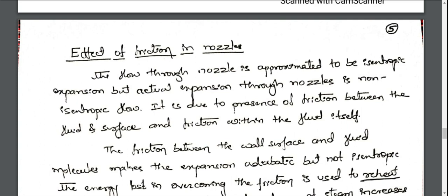The point number one is when the fluid, that is steam, passes through the nozzles, expansion takes place. So what type of expansion is it? It is a reversible adiabatic expansion process. Reversible adiabatic expansion process is also called isentropic process. That is, entropy during the process remains constant. So this process is the ideal case. If the entropy is constant during the process, it is the ideal case.